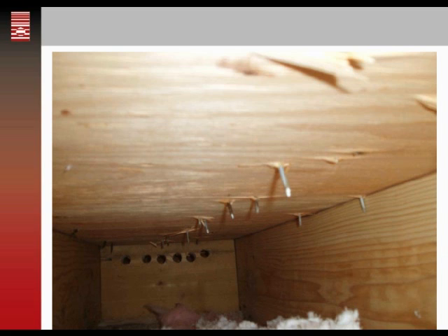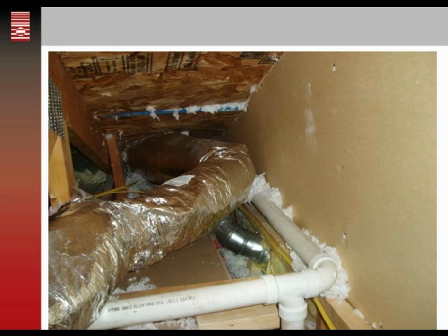So again, it has ridge venting, but that's just venting the air that's leaking from the house out through the attic. If you have low attic venting, it's going to draw up cold air from the outdoors and help keep that attic cold. Ideally, you'd like the attic space to be the same temperature and relative humidity as the outdoors, so you don't have those kinds of heat loss durability issues that you have in cases where that's not happening.